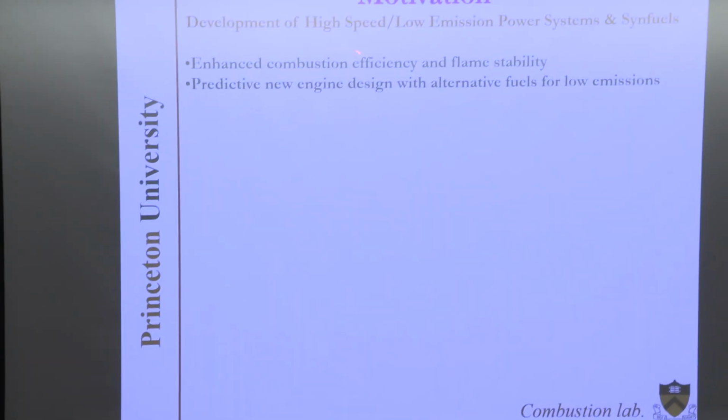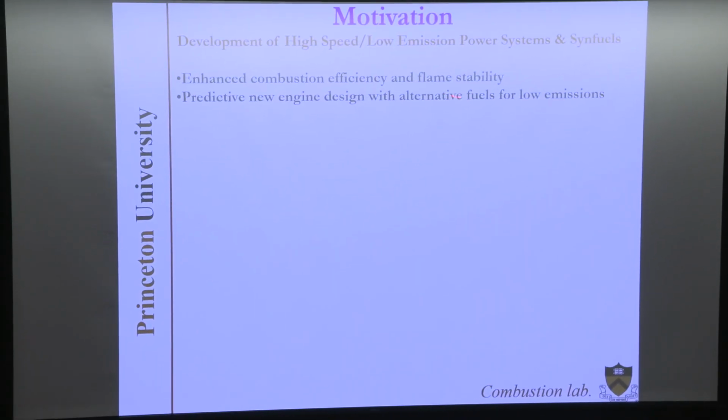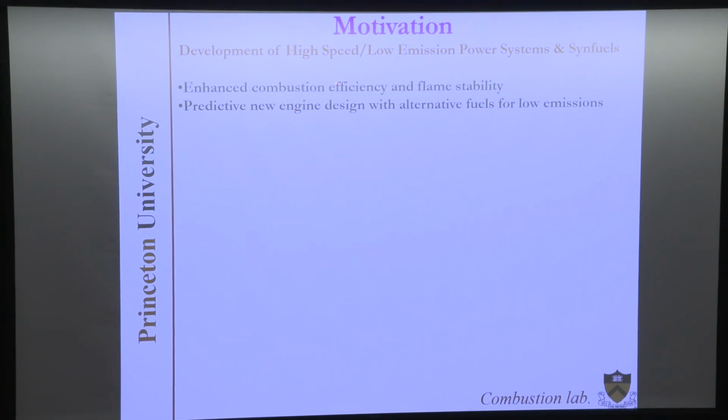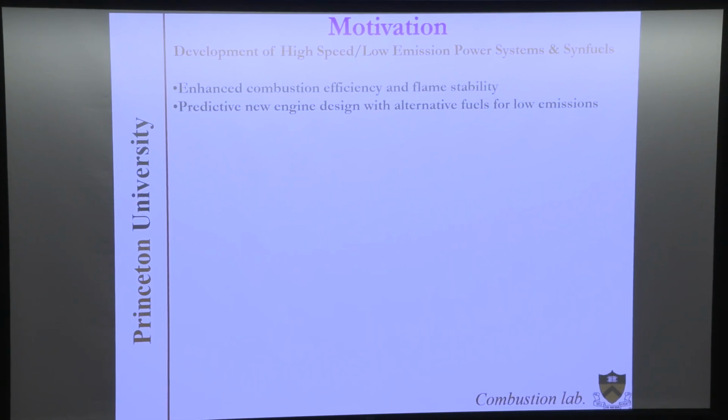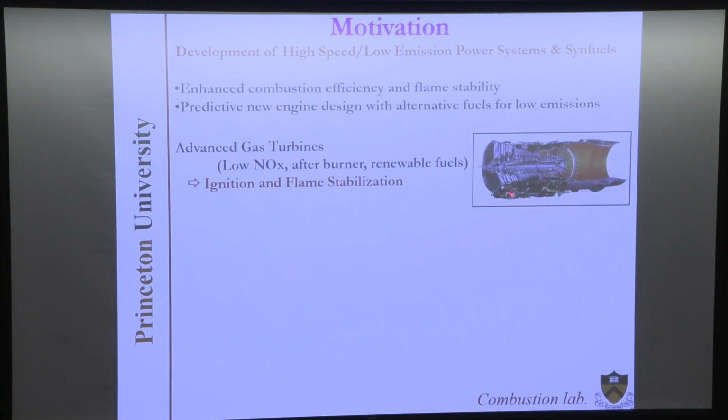I'll share with you that the motivation for using plasma is to control flame instability and combustion efficiency, so that we can develop new engine technologies or new fuels. Today we are running hydrogen combustion, or very ultra-lean combustion to reduce NOx, and fuel flexibility becomes very important with different heating values. Therefore, you need to stabilize the combustion process.